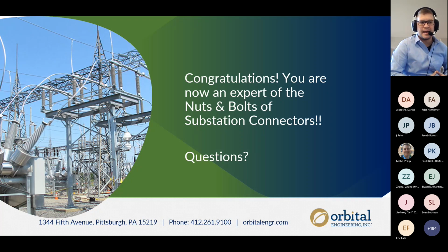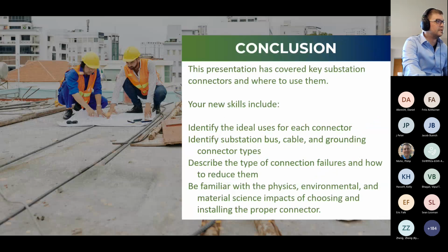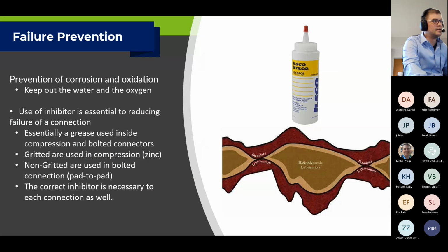But it sounds like the damage is incoming where the water stays in there, and then when it freezes, it expands and cracks, if I'm hearing that correctly. Yep, it is. But like what you said for the breaker situation, drill a hole in the bottom. Any idea what size hole? Typically, I wouldn't be able to give you an exact dimension, but they're tiny little holes. If I go back to the slide with the oxide inhibitor, you really don't need a large hole to even insert those into. So it'd be a similar mindset, just making sure that you have some method for the water to seep out. Okay, awesome. Thank you for the help. Thank you.